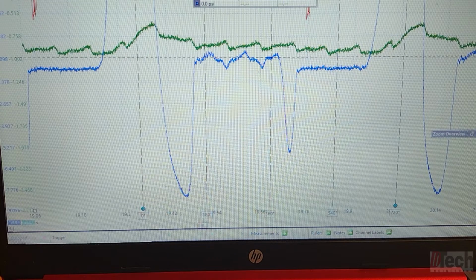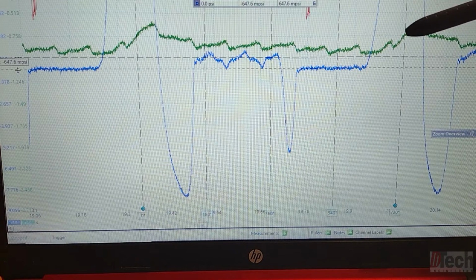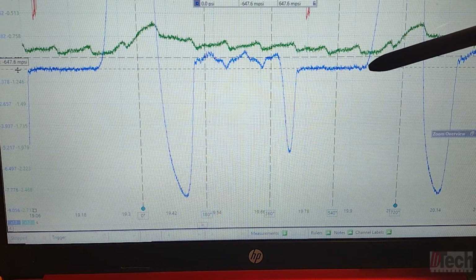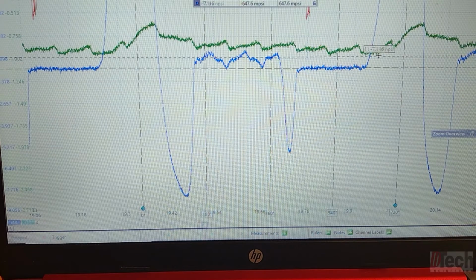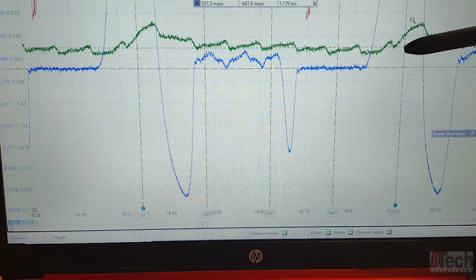We will now look and see where the intake level was at. 0.6 below, so just over 1 inch of vacuum. That is where the closing event occurred. And then now we'll go up on the intake manifold, where we know the pressure started to change direction, which is at that point.